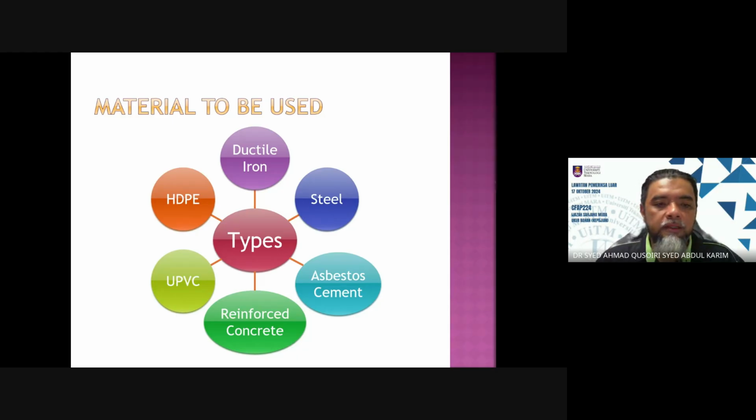You can identify this HDPE pipe because it's basically a plastic pipe that is black in color, and we can bend them much better than UPVC pipes. It won't break, right? So usually the inlet pipes from outside that supply water into each building or each house are HDPE pipes. They can also be used for internal piping of the structure.